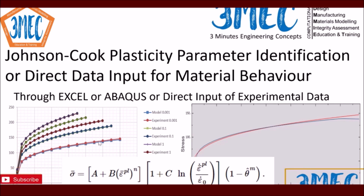So I will show you one way of how to do it. If we are using a Johnson & Cook plasticity model, it has a strain hardening term which has three parameters, A, B and n, dependent on the equivalent plastic strain. Then there's a strain rate sensitivity term, given by this bracket here, where you have two parameters involved, C and epsilon naught dot, which is a reference strain rate, while this is the plastic strain rate, which is dependent on the loading itself. And then obviously the thermal softening part, which will be irrelevant for this case because we are concentrating on the strain rate dependent case.